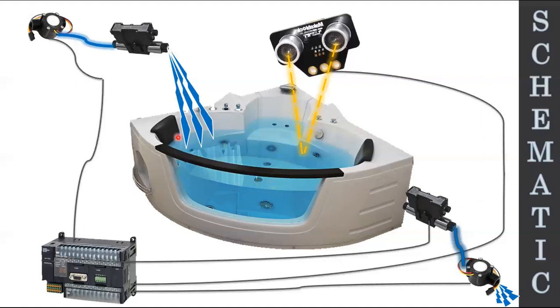So it reaches equilibrium when the flow rate here and the flow rate there are equal, which should be sensed by our system. Okay, so that's why this time we have here a connection from our flow rate sensor to our PLC. Okay, and another flow rate sensor on the drain to the PLC. So the actual flow rate at the inlet and at the outlet are compared here in the PLC.